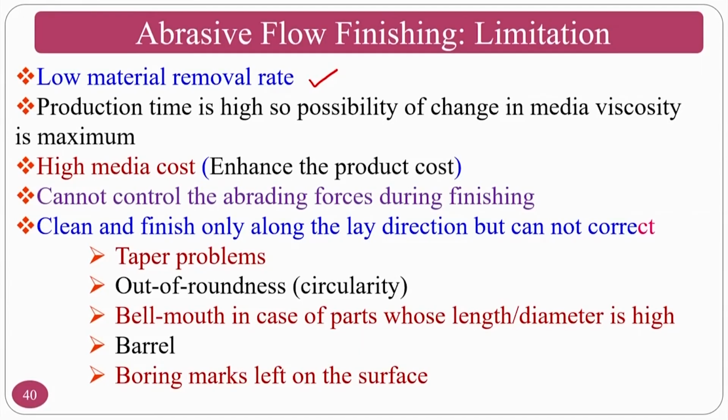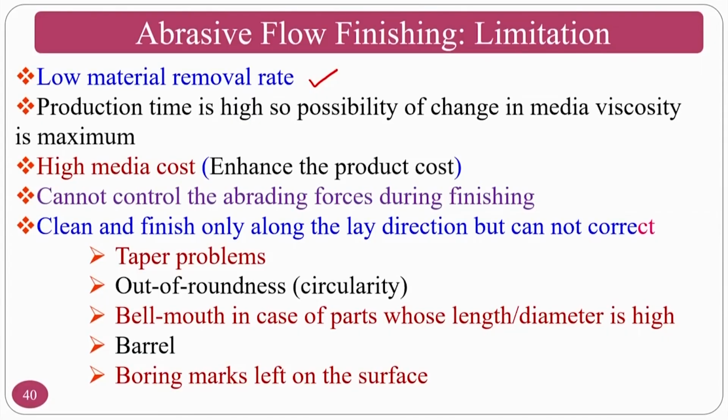You cannot control the abrading process during the finishing because the medium, along with the extrusion pressure, will decide this. It cannot correct problems like taper, out of roundness, bell mouth, barrel and boring marks. This particular process can only finish the surface but not change the shapes, because the material removal in this abrasive flow finishing process is too less.